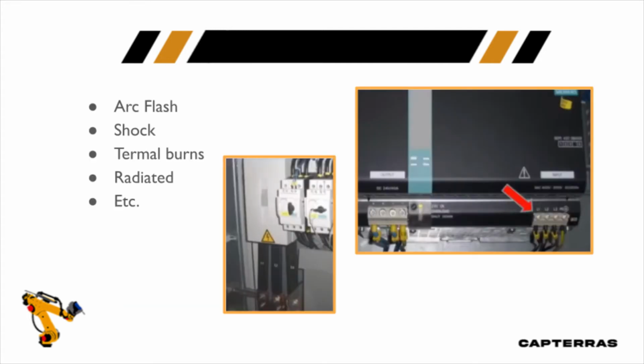And I'm just going to show you an example. I mentioned shock protection early on, but here's a site where we did a risk assessment. And a lot of times people forget about production equipment when they talk about risk assessment. In other words, we went out and we assessed our motor control centers, our switchboards, our panel boards. We put arc flash and shock hazard warning labels on it and so forth.